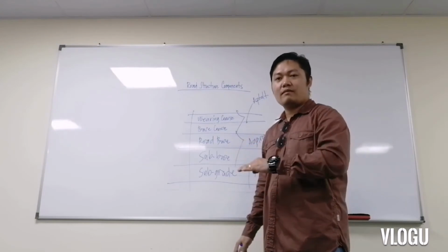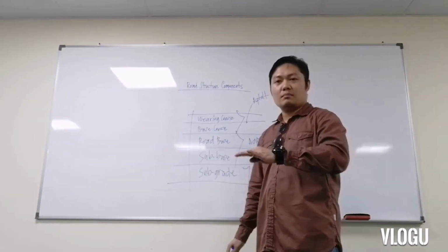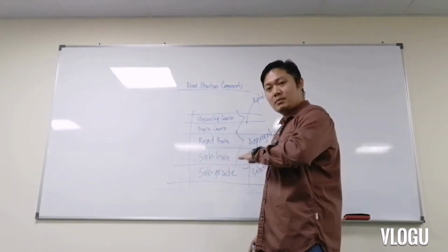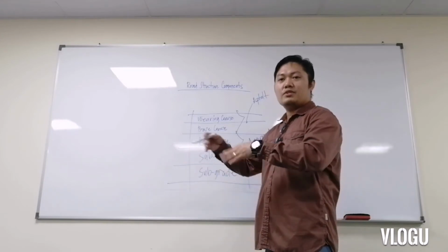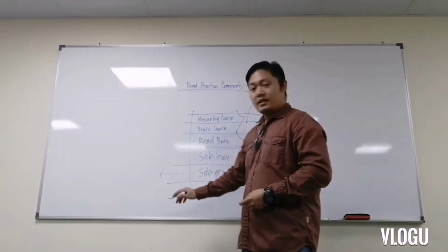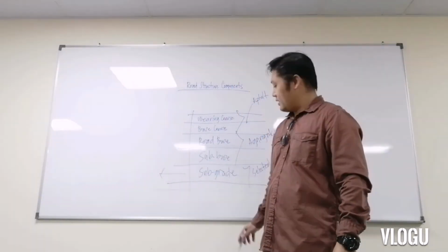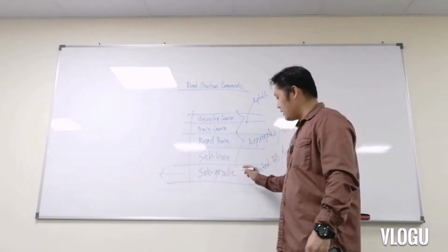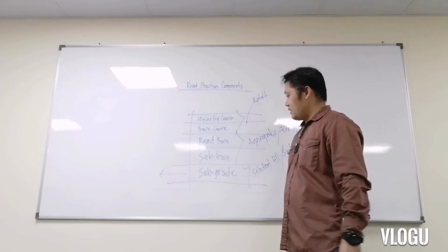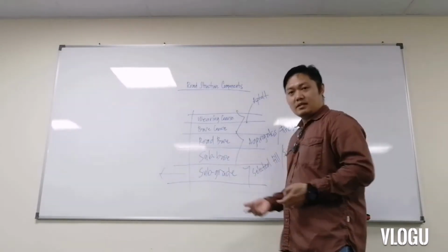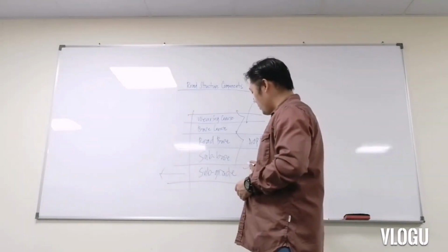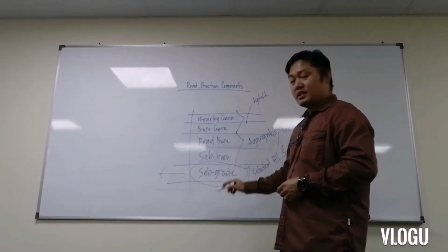The geotechnical survey identifies whether these locations are suitable to be considered a subgrade, because we are going to conduct geotechnical investigations and determine the suitability of the subgrade, in order to ensure that this road foundation will withstand the traffic load that will be carried in the near future when it becomes operational. Normally, before we construct the road, we conduct a geotechnical survey.